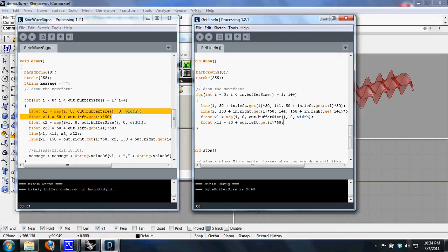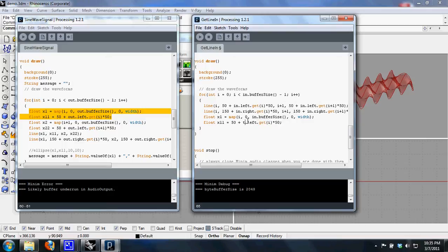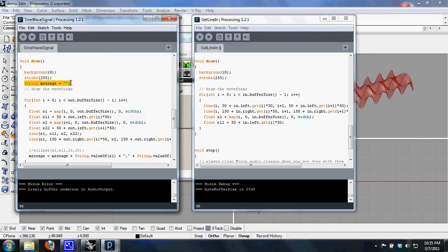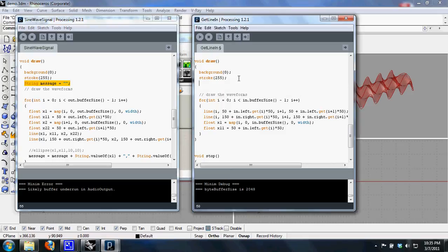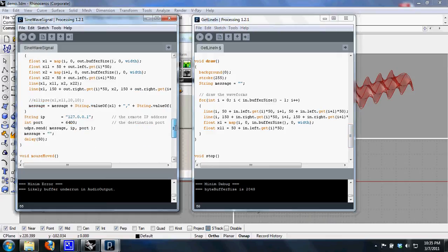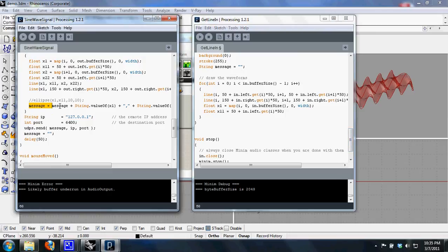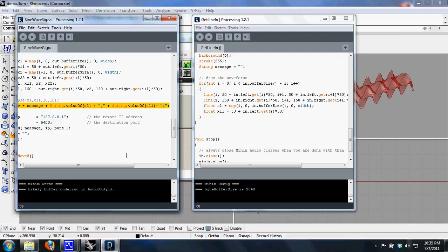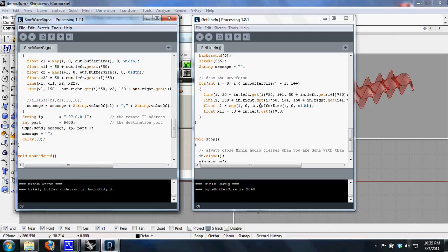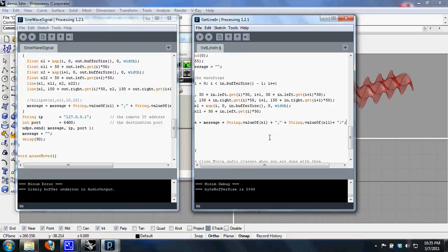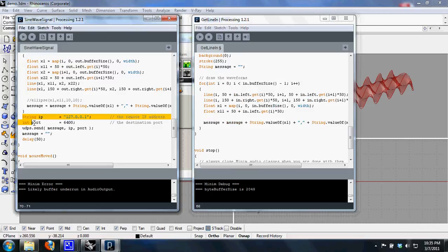And then also in draw, we want to create a string message. The UDP component sends strings from Processing into the Grasshopper definition, and it knows how to handle those and draw these waveforms in 3D. So that defines the message string, and we also want it here too, and that I believe is still inside the brackets. Yeah. So we'll copy that message-related string over, and then everything here for string, IP, and insert. These are all in the gHowl script. This is the IP that it's listening for and the port that it's listening to. And that should be everything that we need.